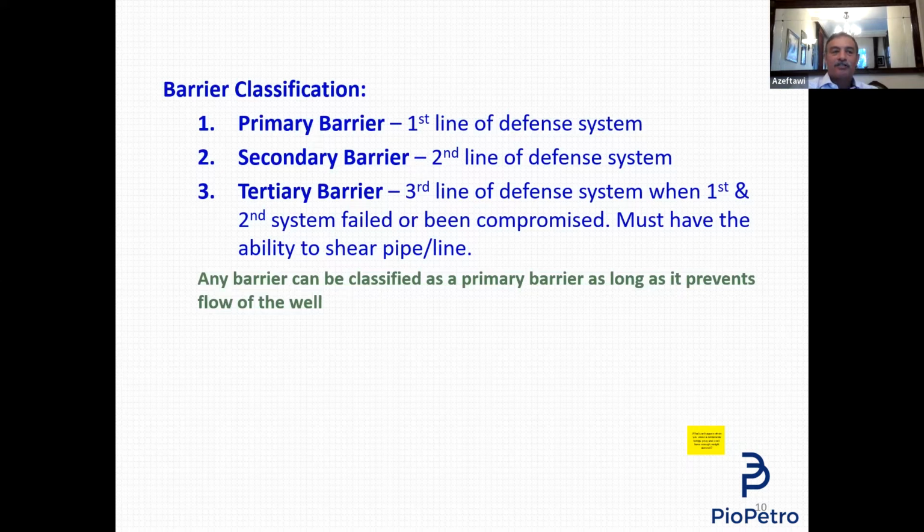Let us assume that you need to do a perforation job, that you need to go with E-line. You run in the hole 3,000, or make it 13,000 feet deep. Then with what we call perforating guns, you need to perforate. You shoot guns that penetrate the casing and penetrate the formation itself. Then you have these holes, which allow the flow of the hydrocarbons into the well.